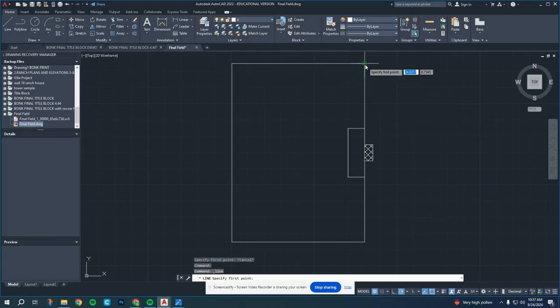Click the line tool, hover over the corner point. As you start to drag downwards, you're going to see extension, which is the distance that you're dragging along that line. If you just type in 1 and then enter, it's going to start that line that needs to go 1.5 inches, 1.5 this way. It's going to start it exactly where it needs to be. I'm going to enter again. And you can do the same thing from the bottom here. You can mouse over it, start to drag along, and extend, hit 1 and then enter, and it's going to make a 1 inch offset line, and then I can just type in 1.5. Escape key, turn the line on. So there's evidently multiple ways to do the same thing.